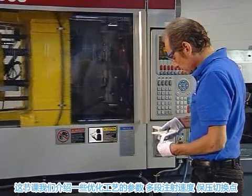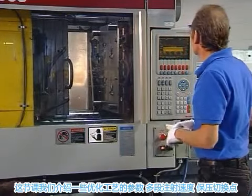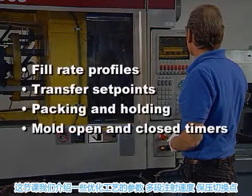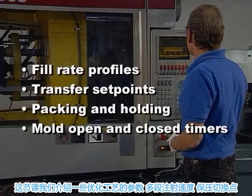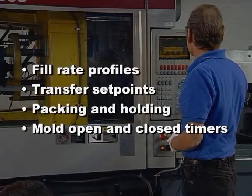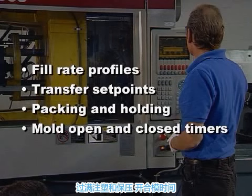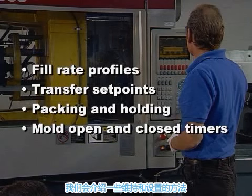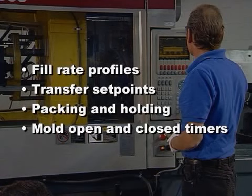In this lesson, we will look at ways to optimize the injection control settings for the molding process. These settings include fill rate profiles, transfer set points, packing and holding controls, and mold open and close timers. We will describe rules and procedures for setting and maintaining each of these controls.